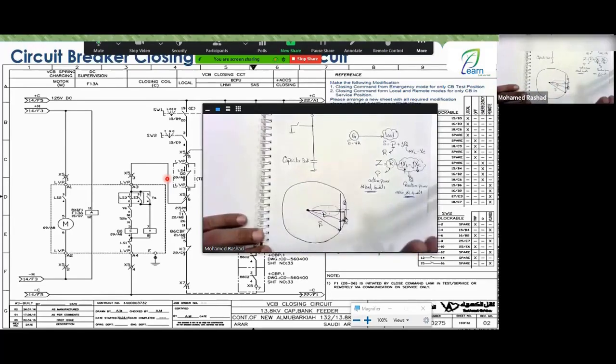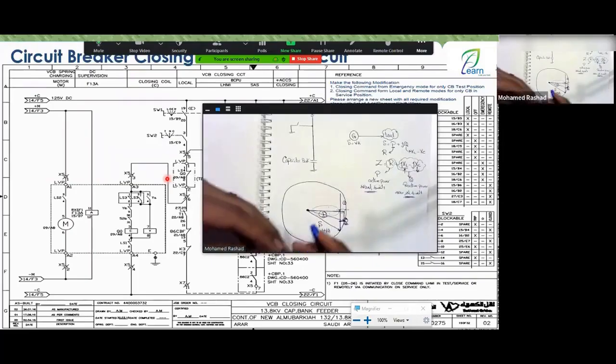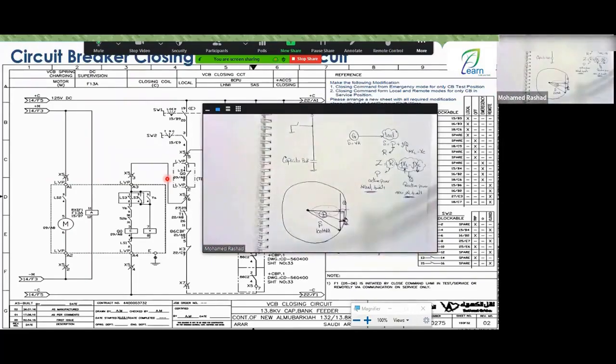Not everything is about money. But if I charge you for Q, if my generator produces 100 MVA with 50 P and 50 Q, I will charge for them. Yes, but those 50 MVA of power will only be useful for 3 or 4 subscribers, for example. All right, why? Because in essence, if I draw Q, I can't provide power to other subscribers, even if I collect my money for the Q. This means I have to build many power stations to supply all my loads, right or wrong?